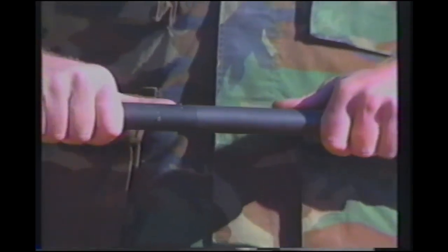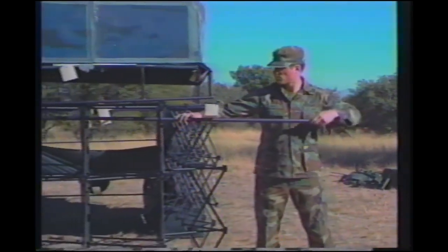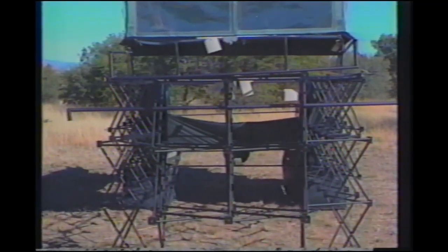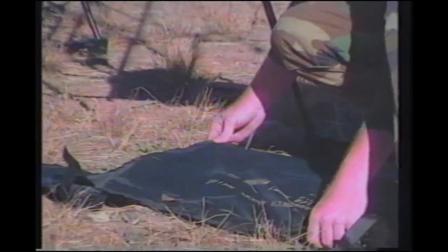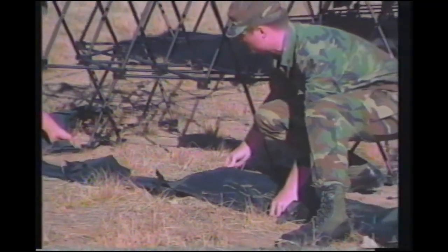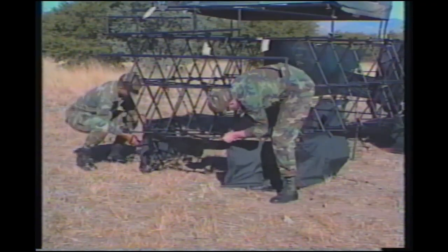The front fender support bar is installed by placing the bar through the center of the front hood scissor section. No attachment is needed for this bar. The front lower wheel skirt with differential is attached by fastening the grommets in the bottom of the skirt to the hooks on the frame. Next, attach the hook and pile strips at the top of the skirt. The stretch cords at the top and bottom of each end of the skirt must now be attached.